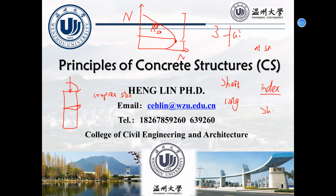The slenderness ratio is lambda. To calculate it, we use the effective height L0 divided by i, which is related to the square root of I divided by A, the characteristic parameter of the section.